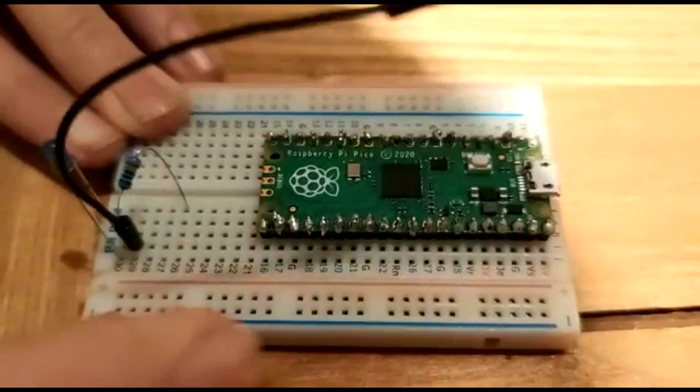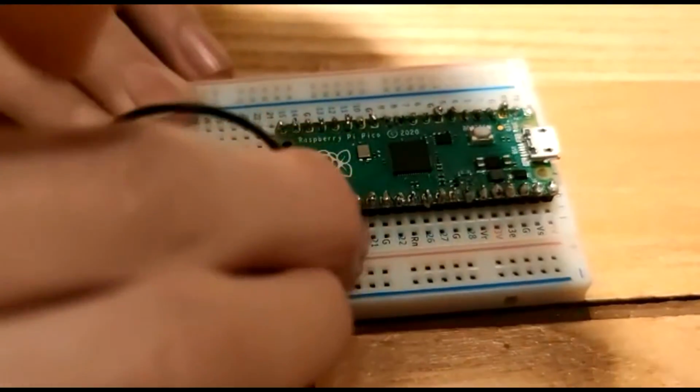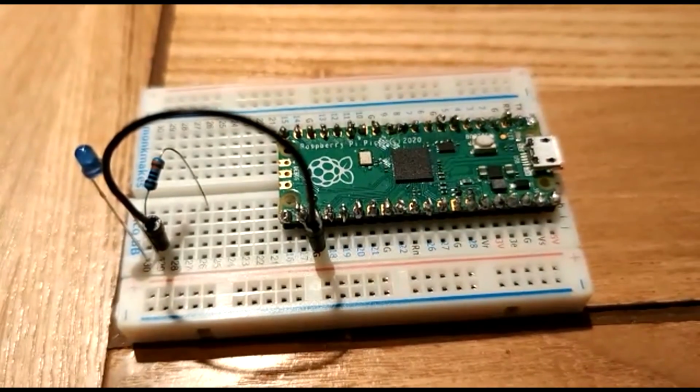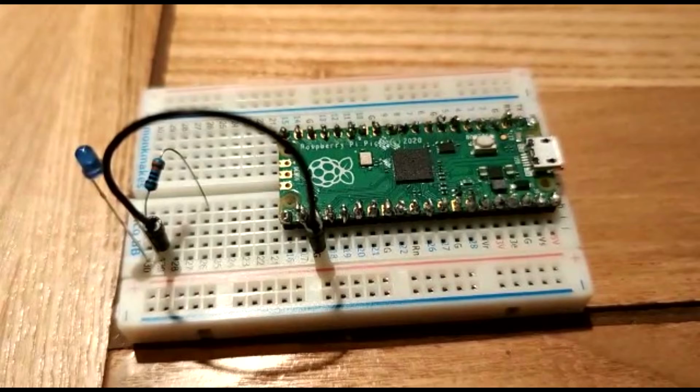Now we are going to need our two jumper wires to connect our LED up to the Pico. Take one side of your male-to-male jumper wire and connect it to the same row that the shorter leg, or cathode, of your LED is connected to. This shorter leg is ground. We can now connect the other side of this wire to any pin of our Pico that is ground. If you are using the breadboard that I am, you will see this labeled with a G.